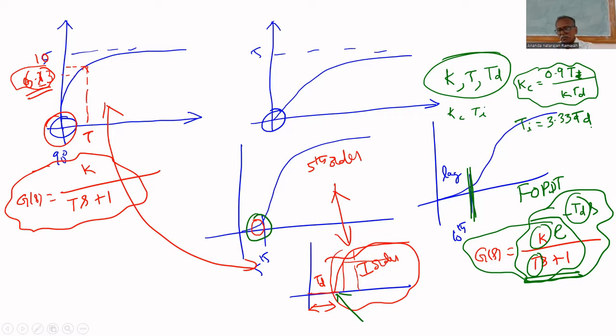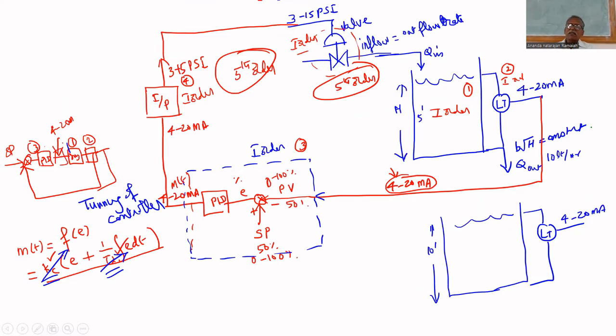How to obtain the mathematical model experimentally? For that, what we have to do is bring this process to 50% first, because always you want to control at 50%. The level is at 50%, outflow rate is different. The level is 70%, outflow rate is different. What is the formula? B root h. Outflow rate is B root h, that is a nonlinear relationship. That's why we have to bring the level first to 50% to obtain the mathematical model.